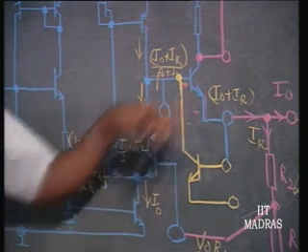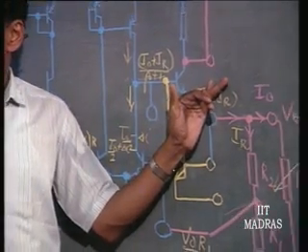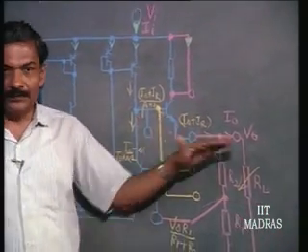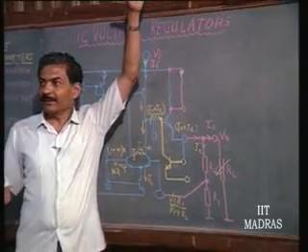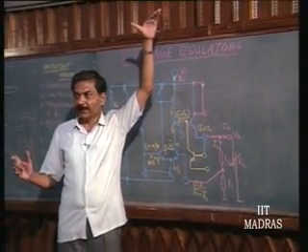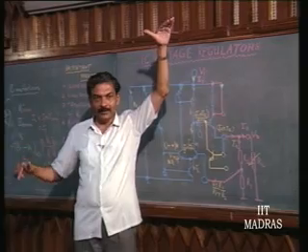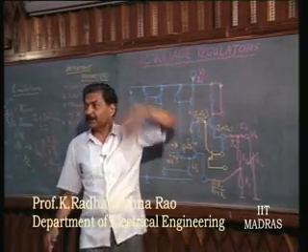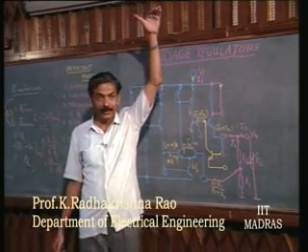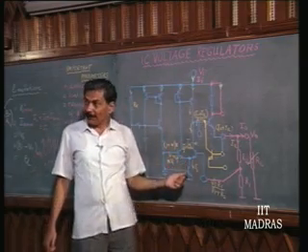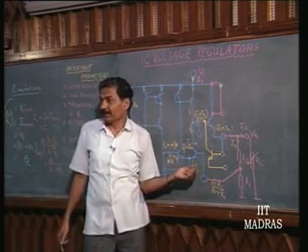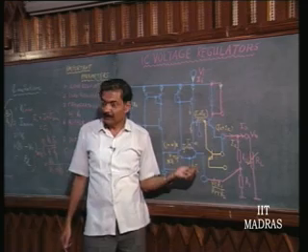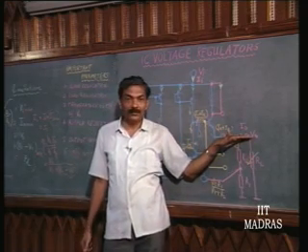As far as this is concerned, you are not bothered about it now because V naught itself is, let us say, very high, because V naught is V reference into 1 plus R2 over R1, corresponding to which Vi has to be still higher. So you have to worry about that Vi max which comes about due to that, not when this is at a certain V naught.